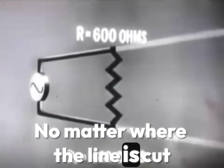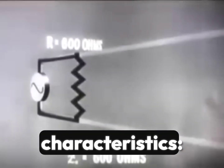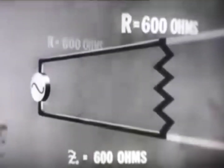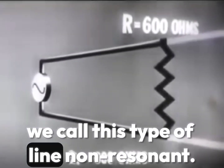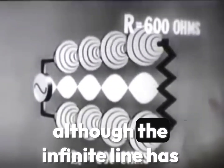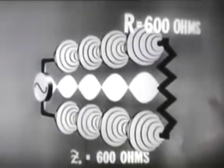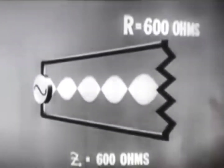No matter where the line is cut and the resistance inserted, the line still presents the same characteristics, voltage and current remaining in phase. Because it behaves the same to all frequencies, we call this type of line non-resonant. Our alternating current patterns still look the same, although the infinite line has been changed into a practical line. For a simpler demonstration, let's use a single part of the pattern, in this case the voltage field.